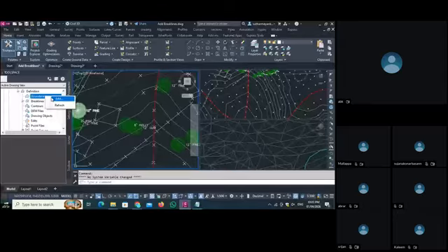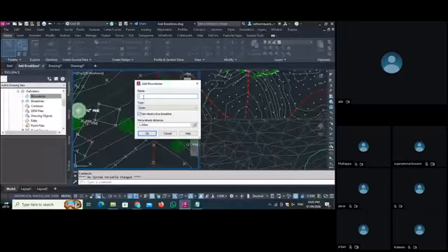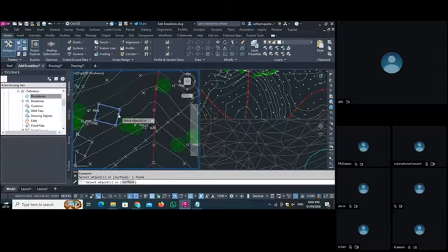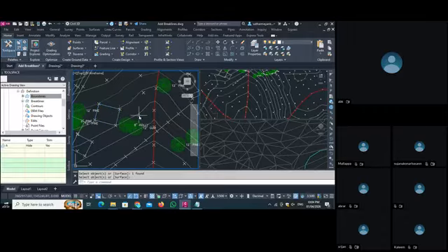We select our boundaries and add our boundary. We can give any name to it. Then if I want to hide the boundary from the contour, I can select hide. For precision also I can set a precision of 0.001 for accuracy. So what happens here? As I select OK, select the object and press enter, you can see your contour is not passing through this object.